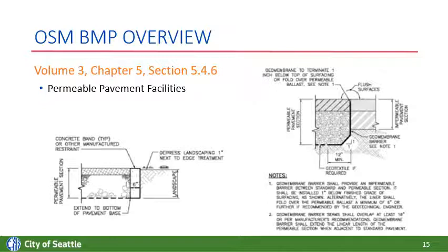So for permeable pavement facilities, new edge treatment figures were added. It may be required that you add an edge to a permeable pavement facility for purposes of maintaining the integrity of the facility. And so some details have been added to the manual to clarify that. And a geomembrane edge example is also shown, alongside the concrete edge.